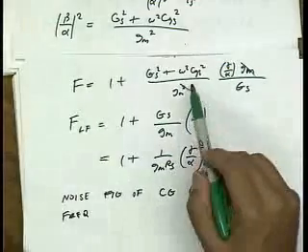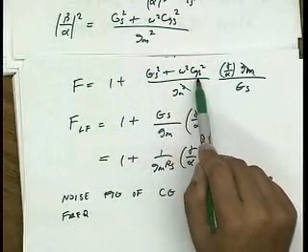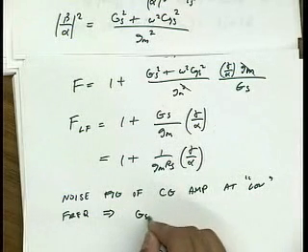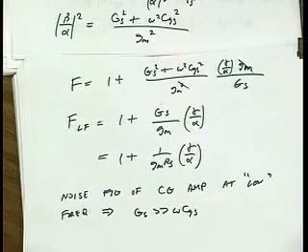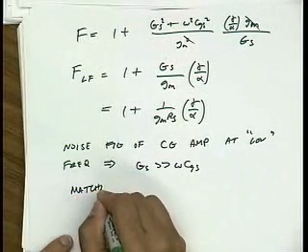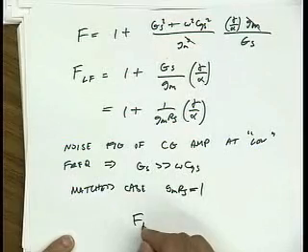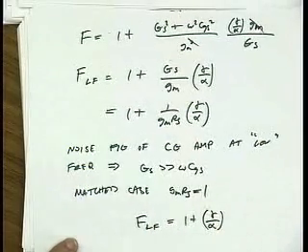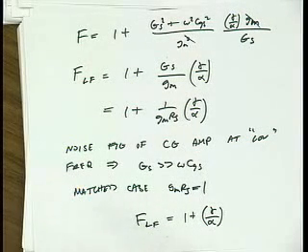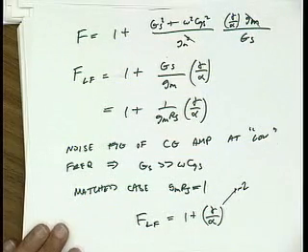You can go back here and see what it means to be low frequencies. It means that at a frequency where the source conductance is much larger than omega CGS. That means that GS is much bigger than omega CGS. And if we have an input match, so for a matched case, gm RS is identically equal to 1, which means that my noise figure is actually 1 plus gamma over alpha, which is in fact pretty bad. We talked about this when we talked about common gate amplifiers. This is one of the reasons why we don't use common gates very often as low noise amplifiers, because this noise is pretty large. This factor might be on the order of 2, so we get a noise factor of 3.